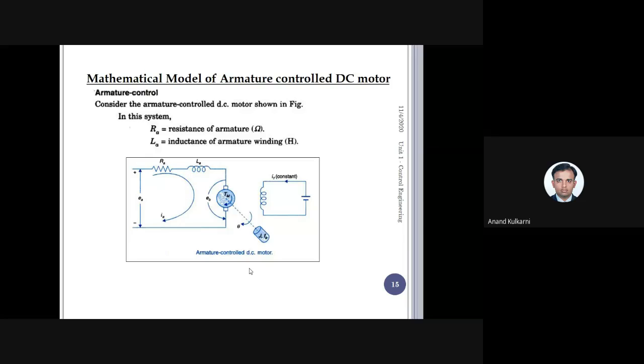So variable frequency drives were possible after the 1980s. Even in the 80s, the cost of thyristor drives was very high, and they were used only for certain traction purposes, like in locomotives. Even till recently, Indian Railway used to use the DC drive only. Even till 4 years back, most of the local trains in Mumbai used to run by a DC drive. DC series motors were used in that. The reason is that electronics circuitry was not easily available or was very expensive.